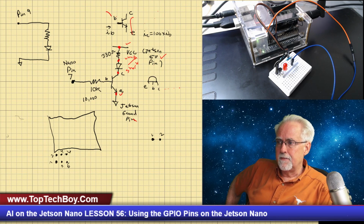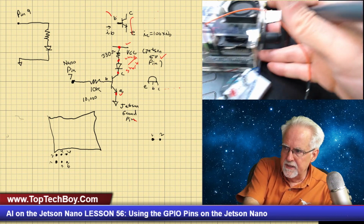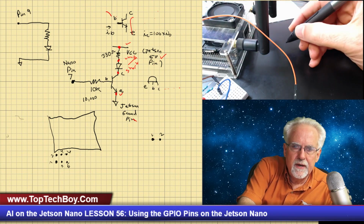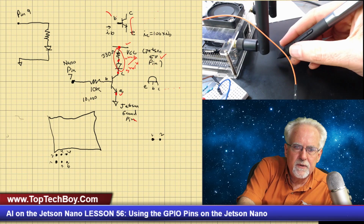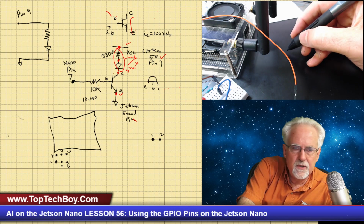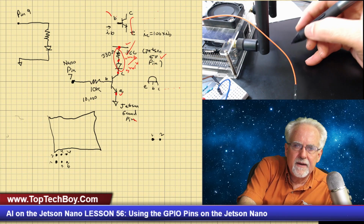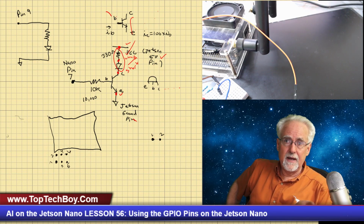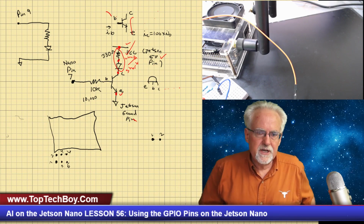But it's hooked up basically the same. The key thing that you've learned today is that if you are going to run something, you put it in a circuit with a transistor, and you use the GPIO pin to turn the transistor on and off, and then that gets its power from an external power supply. In this case, the 5-volt pin of the Jetson Nano.